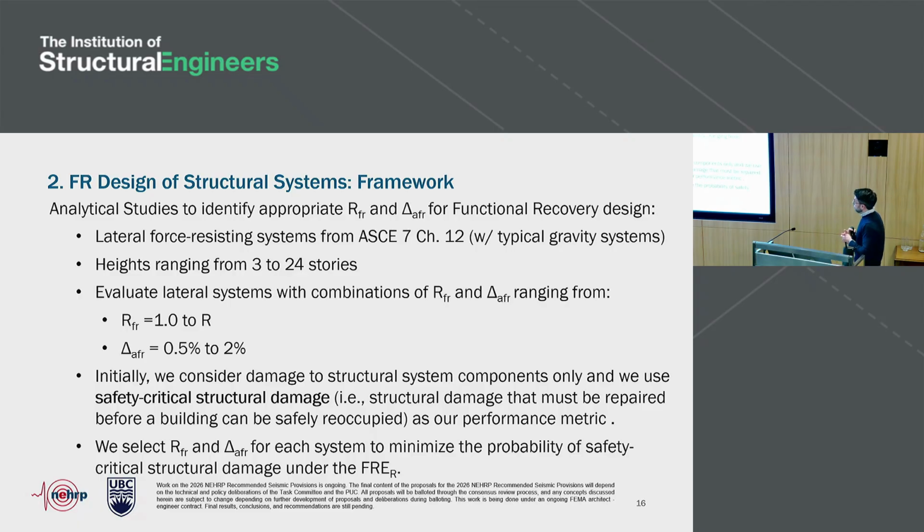Okay, so in essence, to come up with RFR and drift limits for functional recovery design for this range of systems, we're effectively looking only at a subset, as I showed in the previous slide, and thinking both of the lateral system in combination with a gravity system, right? Because damage to the gravity system can equally lead to essentially a lengthy recovery time.